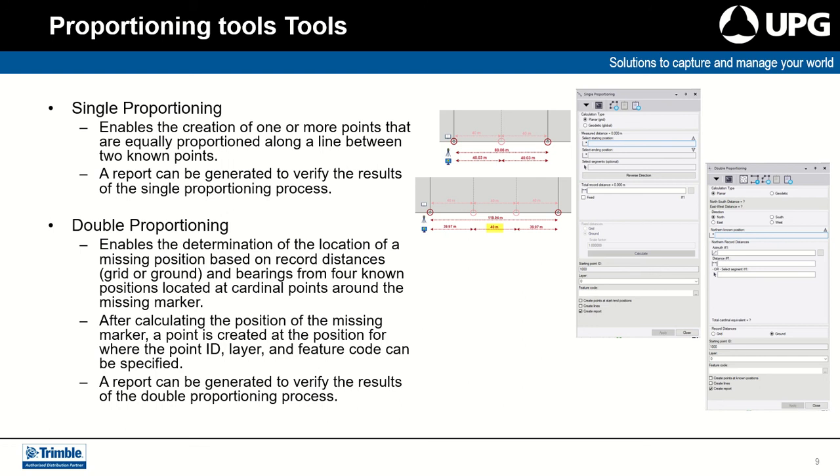A better example may be the example below, where there are 3 lots where we want to split 119.94 up into 40 metre lots. You'll notice that the central lot is 40 metres because we can meet that parameter, and then the two side lots are 39.97 metres. This will make that calculation of lot boundaries a lot easier if you're trying to subdivide a lot.